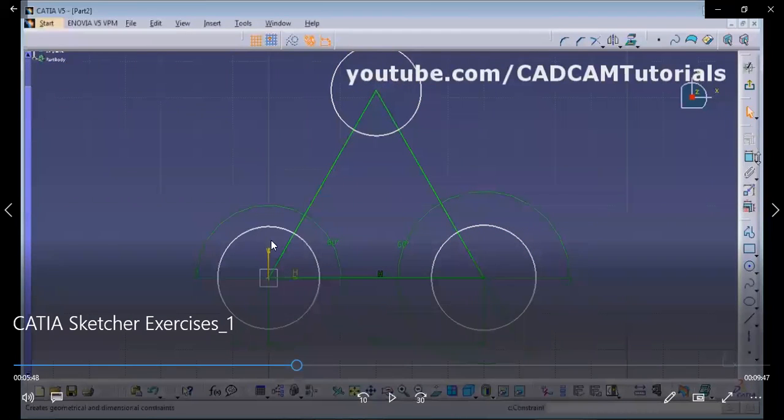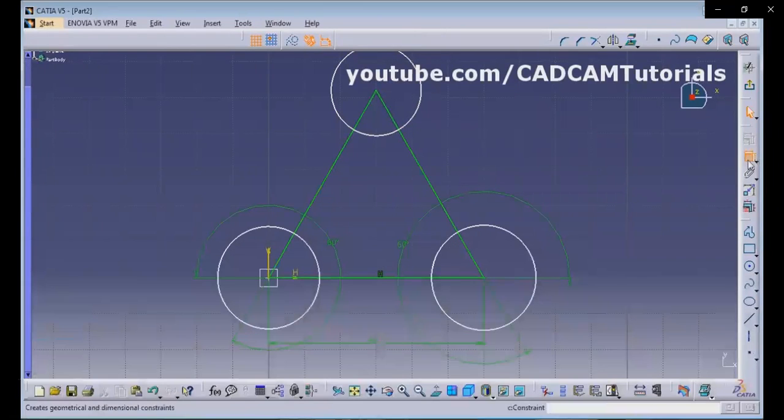You don't confuse that green to be a circle. That is a dimension. It should have been here. We can even manipulate that, but he kept it there. So this is not a circle. That's your angular dimension. The ones in white are your current circles. Double click the constraint and give the dimension,